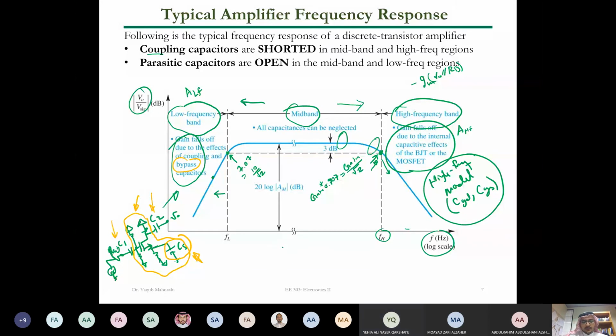So you have the application, and I'm going to choose 1 gigahertz of course. The theoretical and ideal logic says you take all of them, right? You have no problem with any of them. The amplifier that gives you 1 gigahertz should be fine, 2 gigahertz should be fine, 1.25 should be fine, right? But in real life we don't do that. We usually have some safety margin. So if you want 1 gigahertz operation, it's much better to use slightly higher than 1 gigahertz. So maybe we use 1.25 or 2 gigahertz.